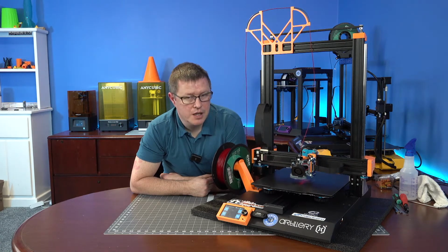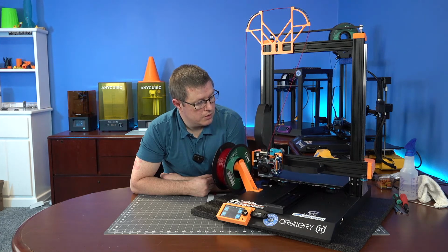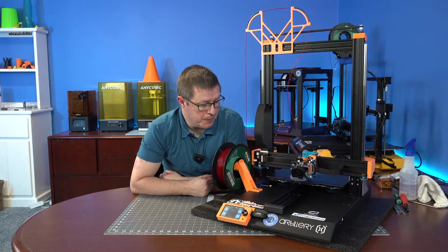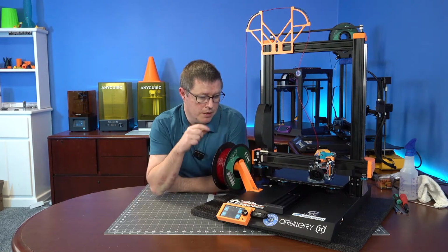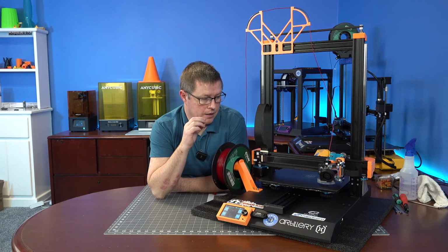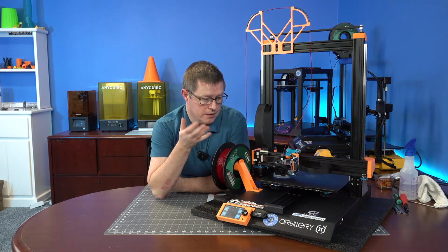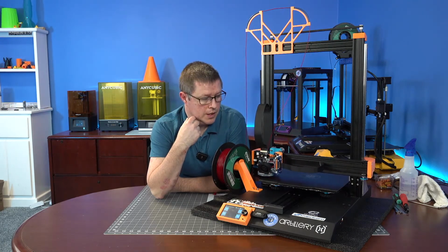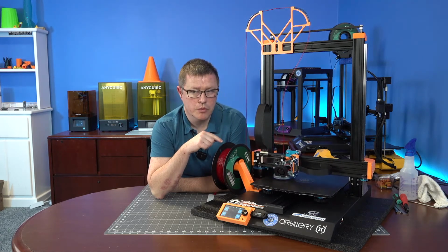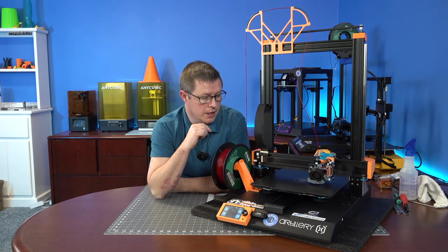And one thing I've set up in the firmware is high-speed probing, where it just goes from point to point. I did a bunch of different tests between this way and the slow way, and this way isn't any less accurate, and it's considerably faster. So some people like to have this in their start G-code before every print just so they know that it's a good mesh, and this can save a lot of time.